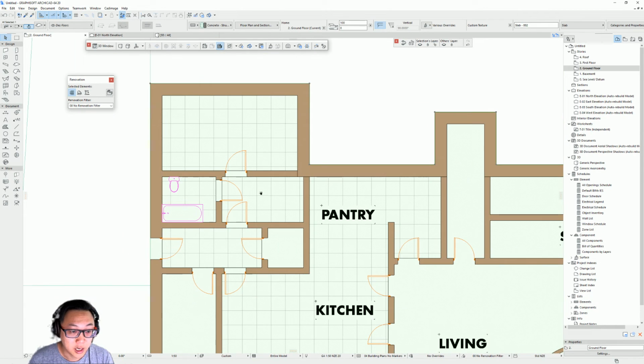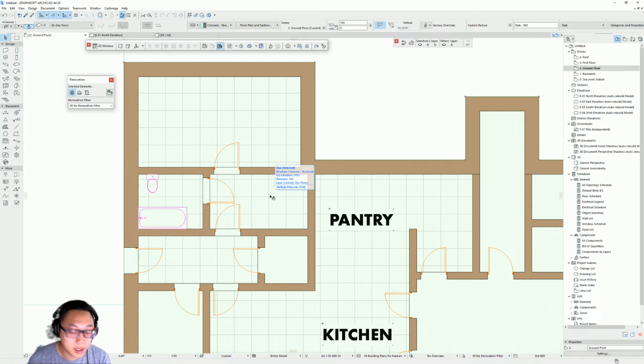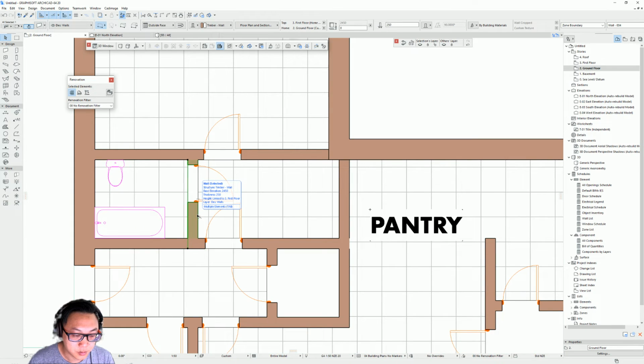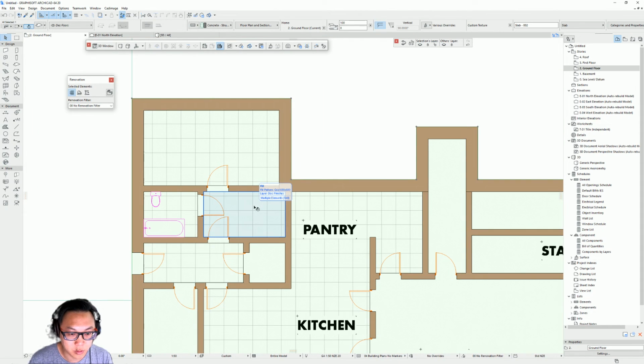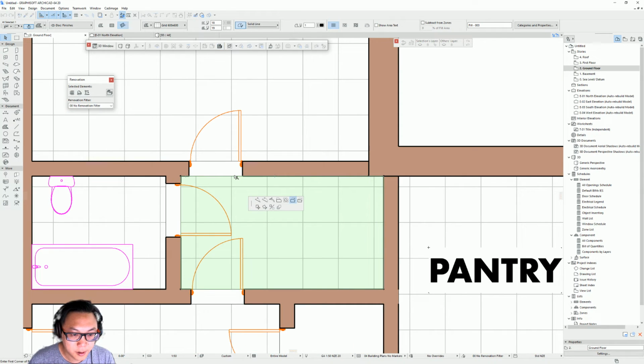As you can see here, I can either select the slabs, but then I want to select the fill. So one way is to press Tab. Tab allows you to cycle through all the things that are overlapped. Let's say for here, there's the wall, there's the fill, walls, fill. Oh, here you get the door, but here, let's say I click the slabs, I want the fill, press Tab and it cycles through. Go onto the edge. I'm just gonna add this polygon between the door.